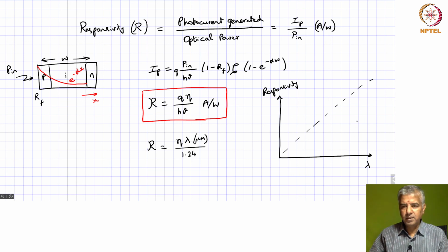But you cannot keep increasing that responsivity. Well, that also brings up the question, can responsivity be greater than 1? Yes, surely responsivity can be greater than 1 because it scales with respect to lambda, okay. Whereas eta cannot be greater than 1 because this is a fraction that's less than 1, and this is also a fraction that's less than 1.